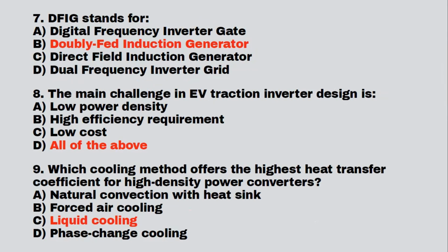Question number 8: the main challenge in EV traction inverter design is all of the above. That means high power density, high efficiency requirement, and low cost. All three, A, B, and C, are correct. Let's go to the ninth one: which cooling method offers the highest heat transfer coefficient for high density power conversion? Liquid coolant is said to be the good one. So liquid cooling is the best one.